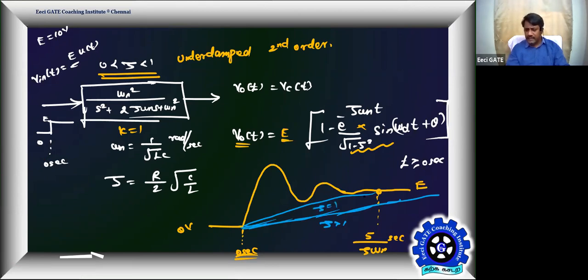I'm taking all these fundamentals from control system so that the conclusions are easier. So this is zeta less than 1 but greater than 0, the underdamped system. So bring all the fundamentals of a second order control system excited by step input into the RLC transients. Charging transient. It is charging from 0 to E with transient oscillations. Decaying transient oscillations. That's how we can conclude instantly.